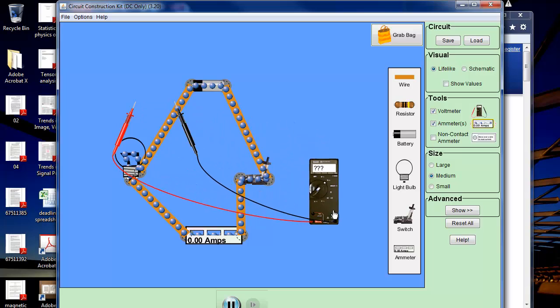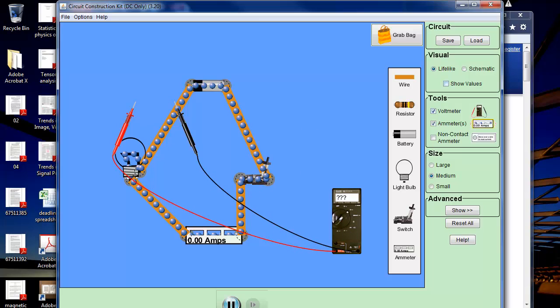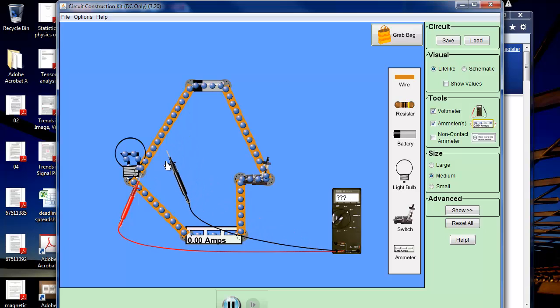Now we also want to measure the voltage, and according to the lab instructions, the positive lead, the red one, red is always positive, should go to where the electrons are coming in, according to what we just saw. The electrons are coming in from that point, so that's where the sticking needle should be. And for the negative, that's where it should go.